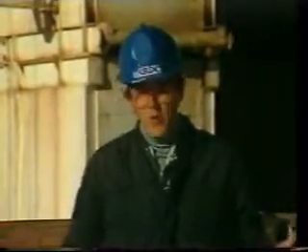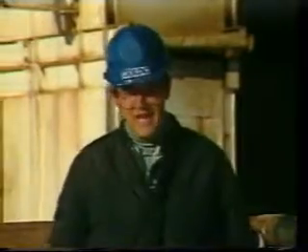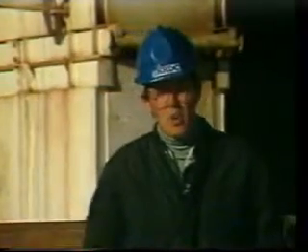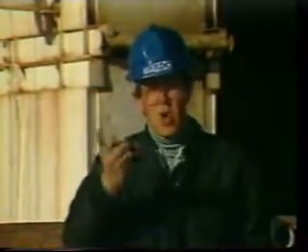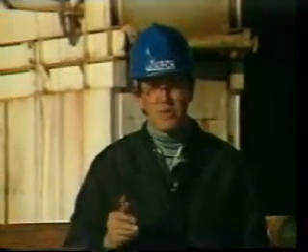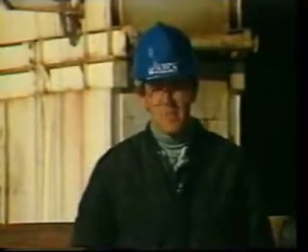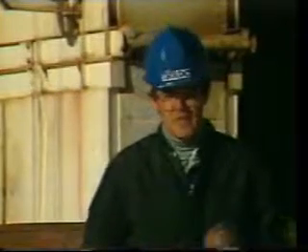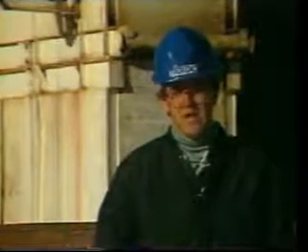When a volume of formation fluid, say gas, flows into the wellbore, it will rise in the hole due to its low density relative to that of the mud, just like air bubbles underwater. As it rises, it pushes mud out the return line, even when the pumps are shut off, and that's a sure sign that we're taking a kick.